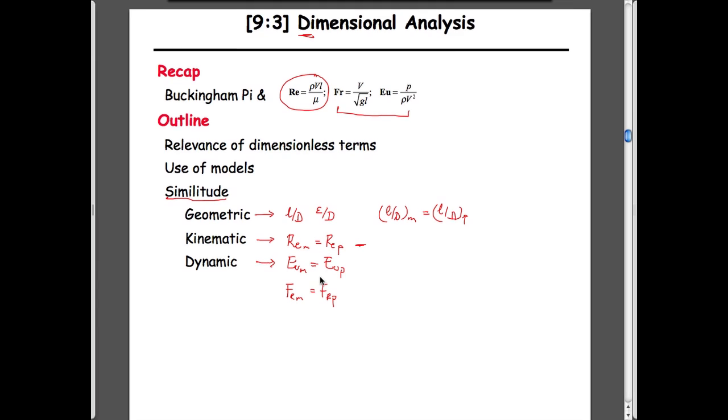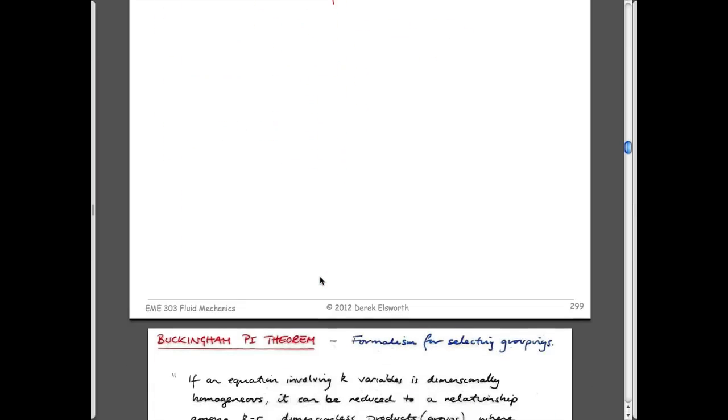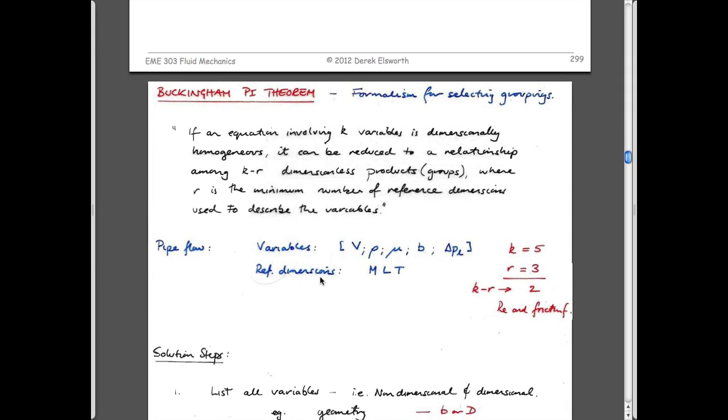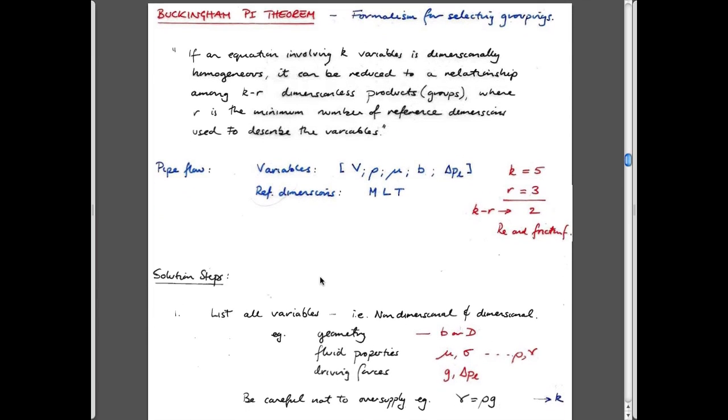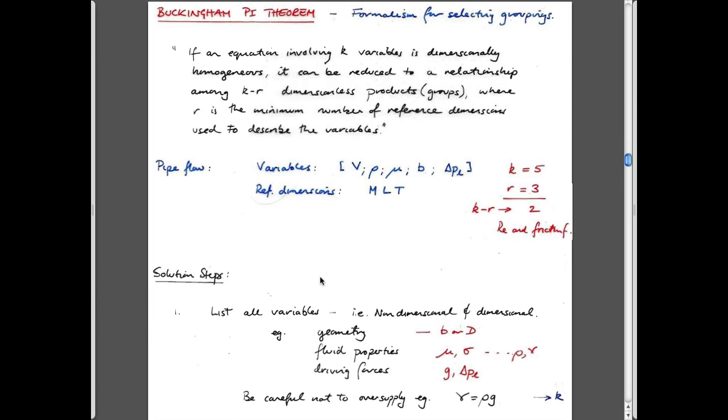There is a formal way of being able to get those. And so if you look in past exams, there probably will be a Buckingham Pi type question. I'm not sure we have much time here to go through it. But the basic idea is that if you can define just the components that define your system, such as, for flow around this dish, some far field velocity, maybe density of the fluid, viscosity of the fluid, some diameter of this, etc., the pressure that gets applied on it,